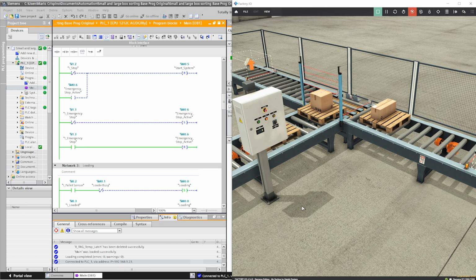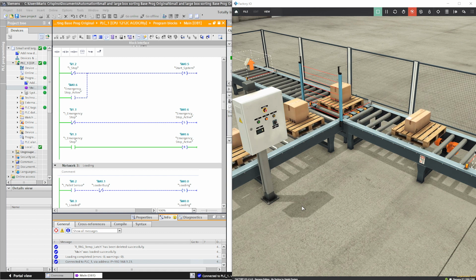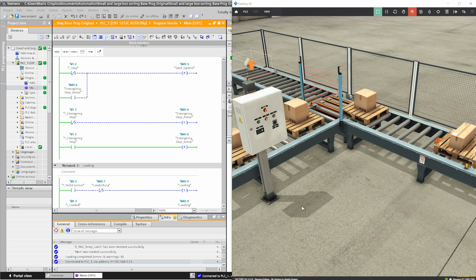You can see the entry conveyor only comes back to life momentarily if a pallet was ready to enter the small loader conveyor before we press the emergency stop button. The rest of the system continues to operate once the emergency stop is disengaged, but obviously it won't continue for very long because the entry conveyor isn't running. All of this is not good from a safety point of view, and we need to add additional logic in to amend it. As it stands, the system can then start up again by pressing the start button, which we also need to make a change to.